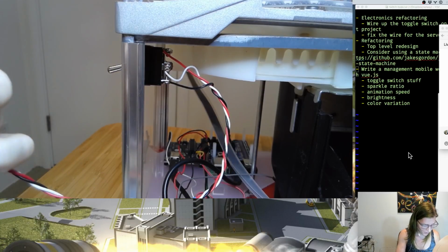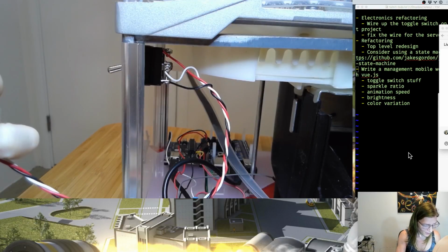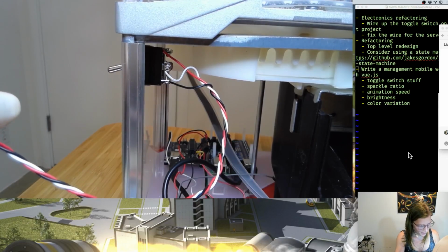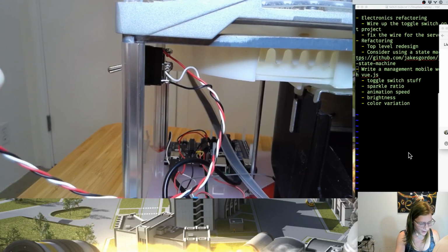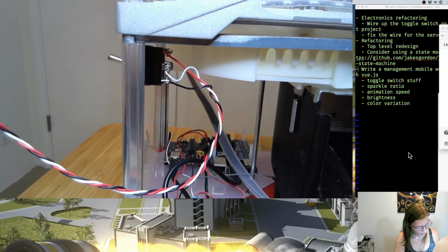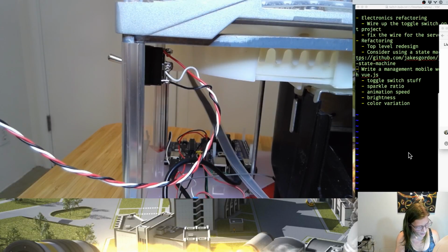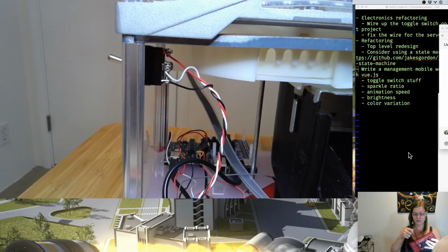It's kind of like running your code every once in a while. You got to check to make sure you didn't screw up something basic like wires touching each other. And hey, they have continuity. I expect the black one to not have continuity and white to black to not. Okay, so if I switch it up, I would expect white and black, but not red and white or red and black. Great. And it's important that red and black don't touch each other because that would be a short and that would make my Arduino turn off.